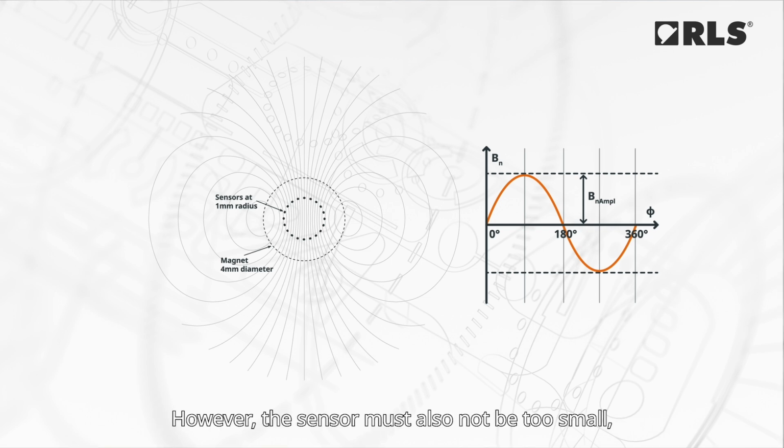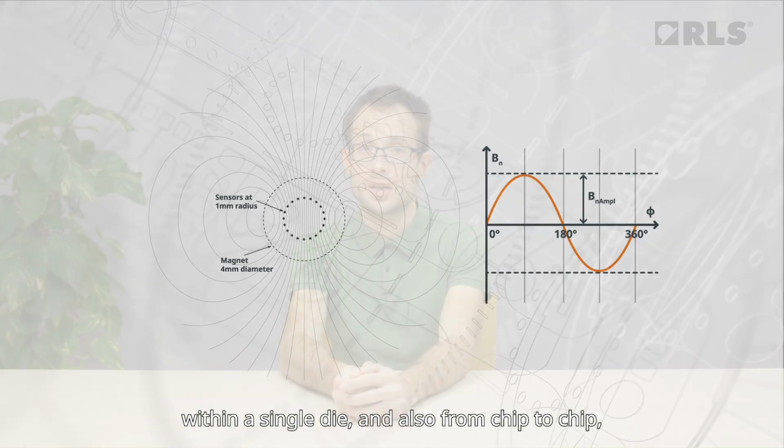However, the sensor must also not be too small, that is, too close to the minimum production tolerances of the microelectronics process. This would significantly increase the mismatch between the sensor parameters within a single die and also from chip to chip, meaning that the image of the magnetic field produced by multiple sensors would be distorted again.